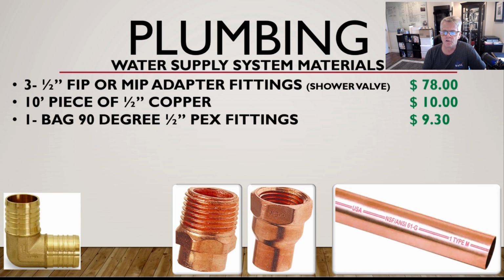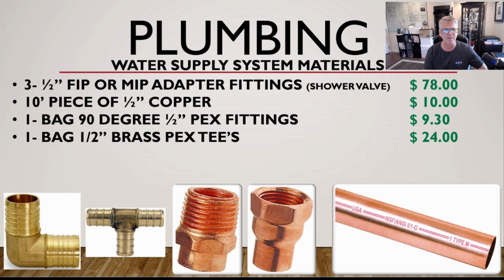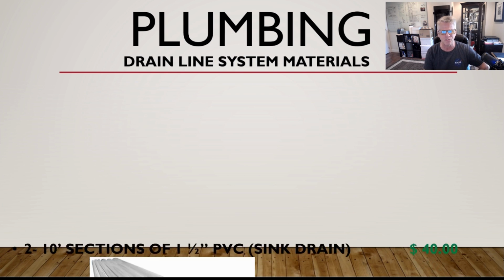1 bag of 90 degrees PEX fittings, and since we're using the PEX water lines, we'll be using all PEX fittings with the crimp rings, so get a bag of those, $9.30. You'll need a bag of the 1/2-inch brass tees to do some takeoffs and other things with those, $24. You'll need a bag of 1/2-inch PEX crimp rings for $17. You'll need a bag of the PEX nail-on straps to secure all your PEX lines, your 1/2-inch water lines, to neaten that up so things aren't flopping around, $3.25.